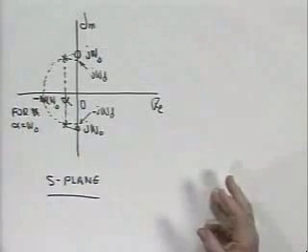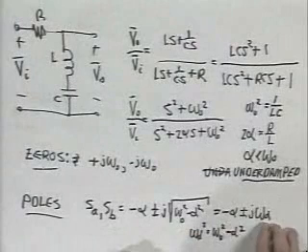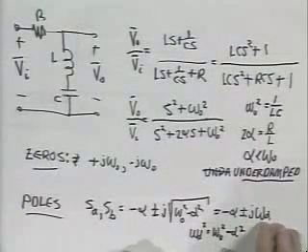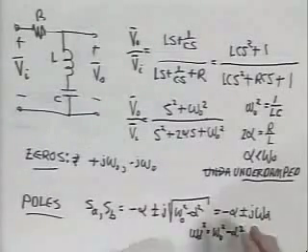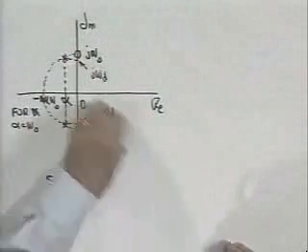If we want the unforced, the undriven, the natural transient response, the natural time domain behavior of the circuit with no forcing, no drive, we set the characteristic equation, the denominator of the transfer function, equal to 0, and its roots are the natural frequencies. If we've done that here, you see the form of these roots. They are in the form of minus alpha plus j omega d. The form of that is a damped cosine, or a damped sine, it doesn't matter. So in this case, the natural frequencies are damped sines and cosines, and we can infer that from the S-plane diagram alone.